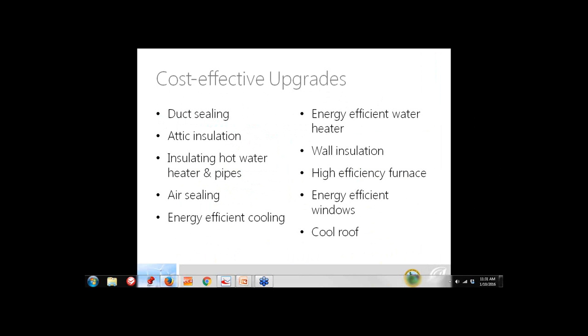Attic insulation, of course, is a comfort both in the summer and the winter. Hot water pipe insulation is a great way to both reduce the noise from hot water pipes, but also to not have to run water, wasting water, trying to get hot water to your bathrooms and kitchens. Air sealing is a very, very key point. There are places under houses and in the attic where you can do air sealing that will make a huge difference in the comfort of the home. This, along with duct sealing, are some of the key strategies for insulating a house.